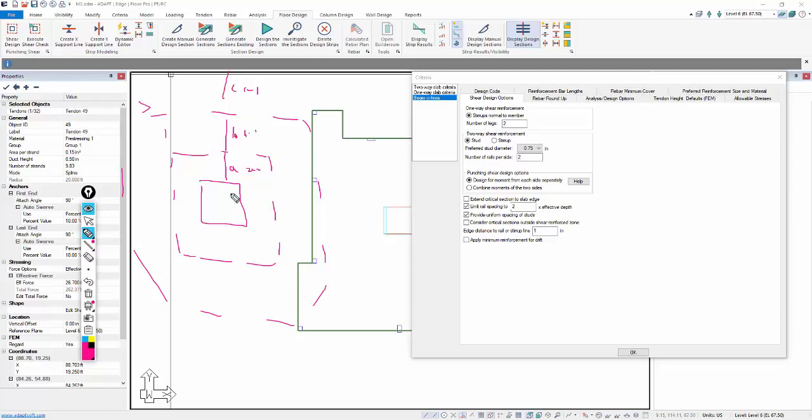And so the program, if you have an output that says you need 3 at 2, let's say 2 at 4, and then 5 at 1, if that total rail length equals 20 inches, the program, when it applies uniform spacing, is going to say take the 1 inch, calculate the number of studs needed to satisfy 1 inch spacing at 20 inch length.